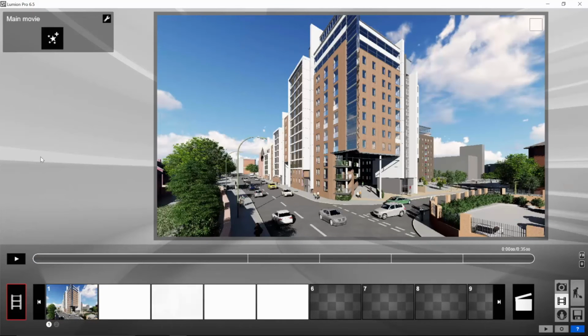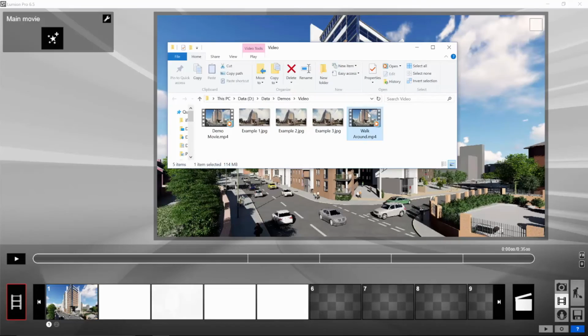I've now taken this a step further. I did render out the movie in the previous screen. This took 15 minutes. Then I inserted the final movie here. I then placed some rendered stills from camera mode, which we were looking at earlier. And then I added transition effects from Lumion to see a smooth transition from still to still. Here is the end result.